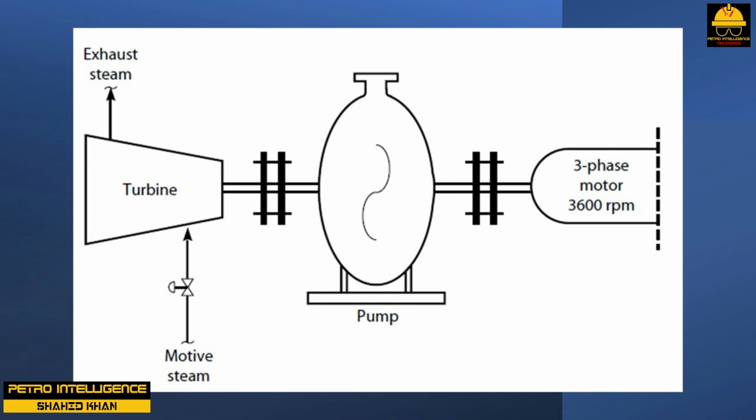That is, the three-phase motor will turn into an electrical power generator. It will begin to export electricity into the grid. A single-phase motor does not have this sort of capability. Another way of expressing this idea is that the three-phase motor acts as a brake on the turbine. The motor can run at only 3,600 RPM as long as it is connected to the electrical grid.